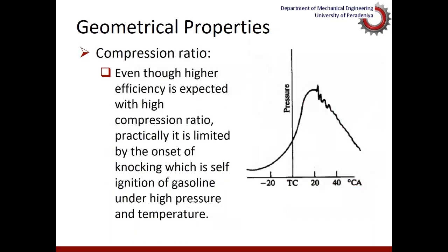That phenomenon is called knocking. It is a very undesirable phenomenon, in which the gases start igniting on their own, particularly the gases close to the walls and the piston crown. We will talk more about this when we talk about combustion.